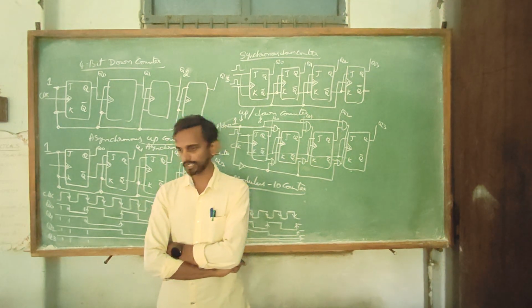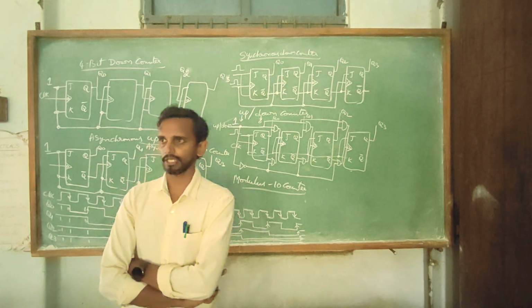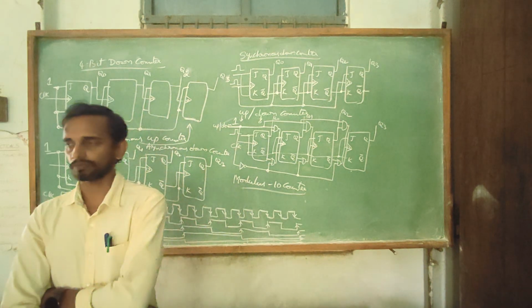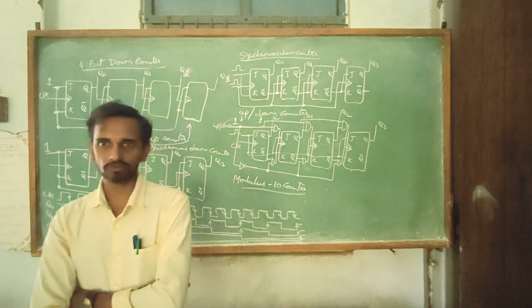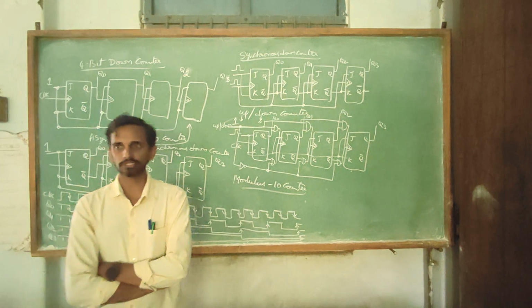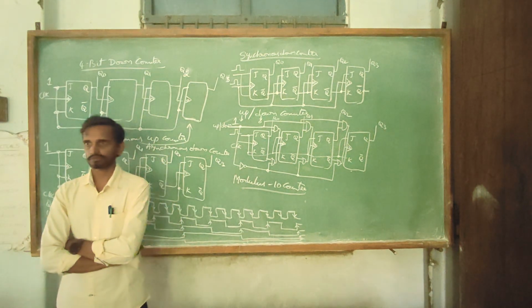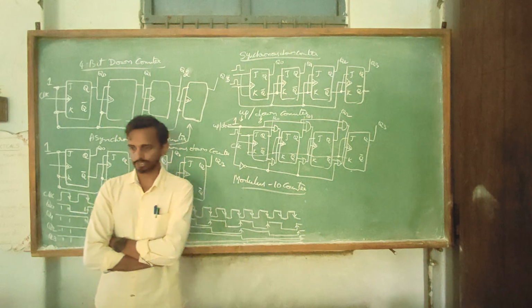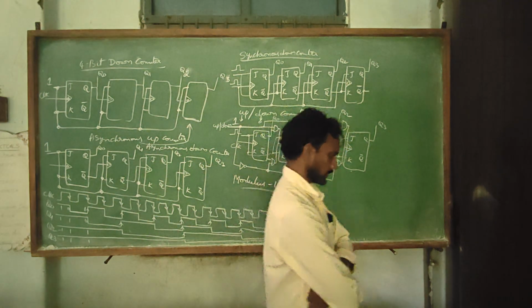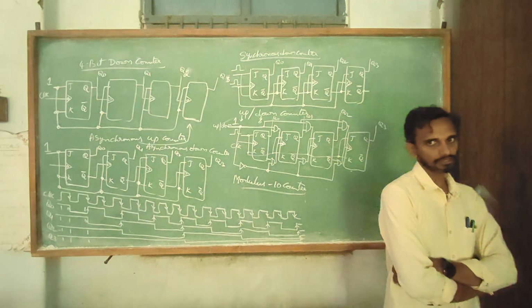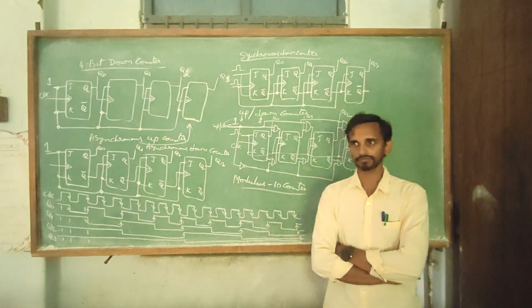If it is a binary counter, it will count all A, B, C, D, E, F, up to 15 numbers. But for BCD counters, we require a counter reset after 9. So counting from 0 to 9, then when 10 comes, the counter has to reset.